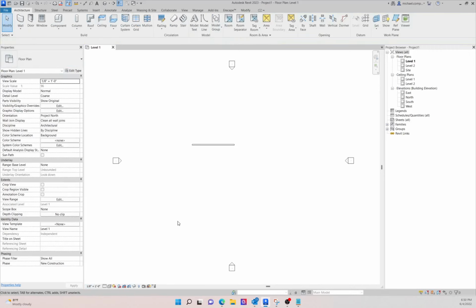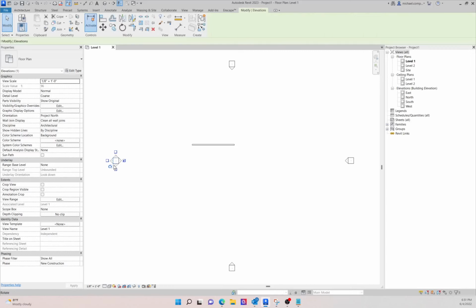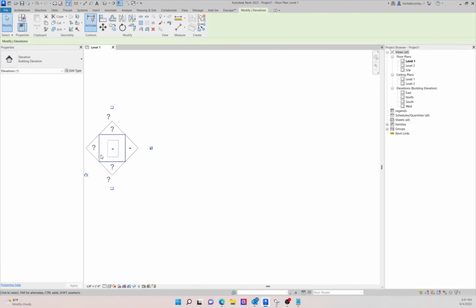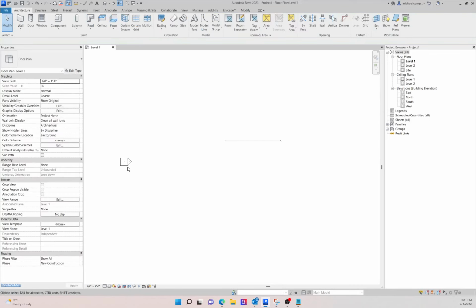So this is the environment you create the model in. And what you're looking at are the north, south, east, and west arrow blocks. This is how Revit identifies an elevation marker. So you have the block itself, and then you have the identifier to show which direction it's looking. So these come with every model template, at least the architectural template, and this is your workspace.